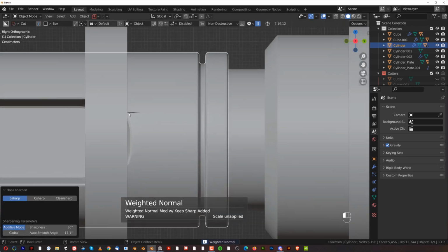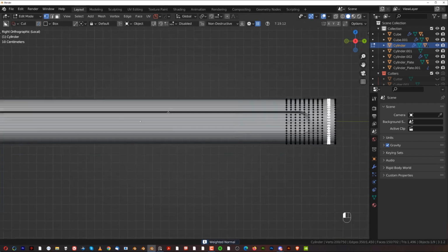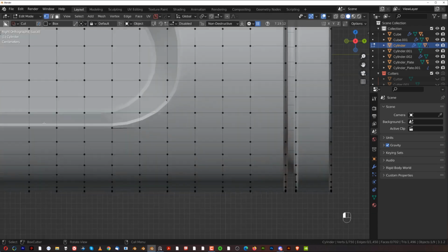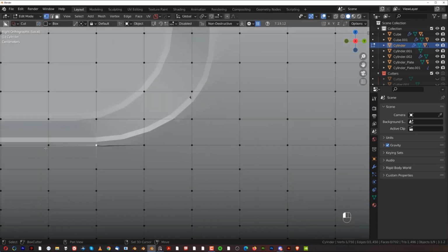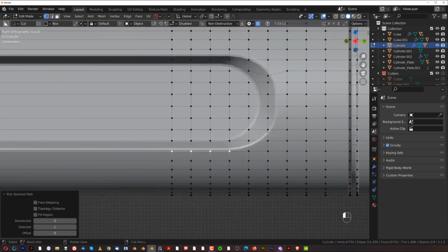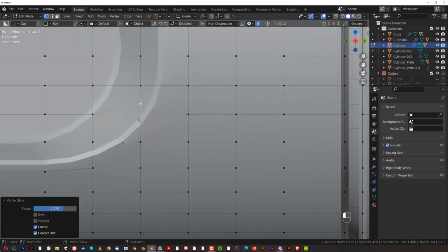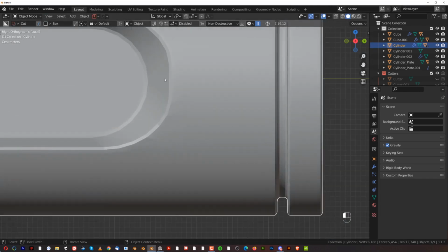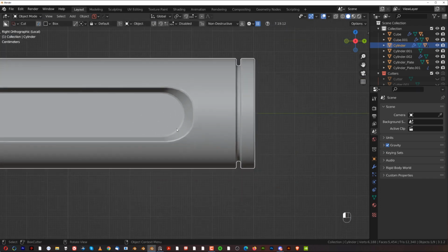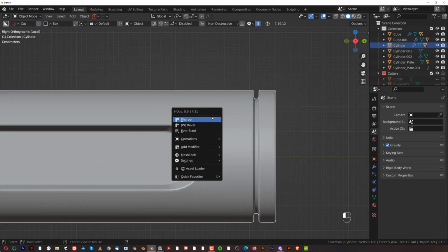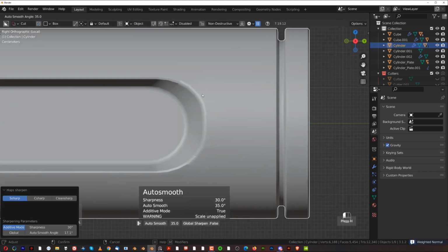Anyway, the normals, you're gonna have some pulls here because of the bevel, but if you have mesh machine, you can always fix this, or just simply move the vert a little bit this way or the other way. You're gonna be fine. So this one is a little bit close here, so we could just move it outside a bit, and this one could be moved inside, and Bob's your uncle. You're gonna have a bit of a bending here, but we could fix this always with mesh machine.